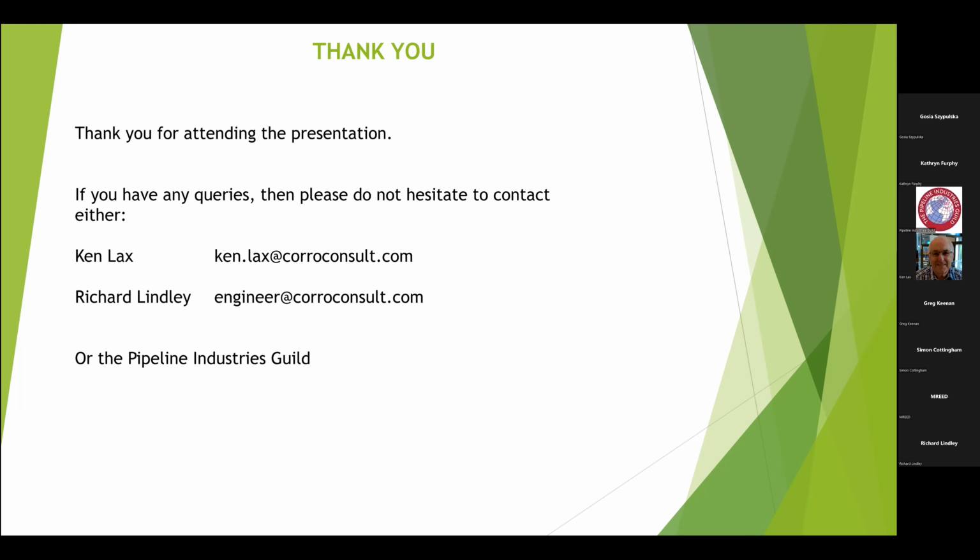So I know what Richard has responded. Richard has responded, if they are protected by the same CP system, then no, there will be no further interference between them at the crossing point. No additional bonding would be required. If they are independent CP systems, that would be different.